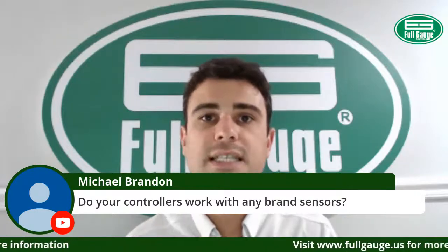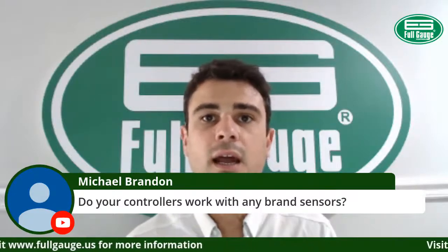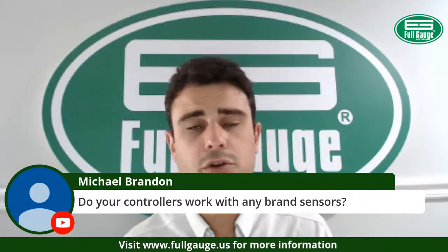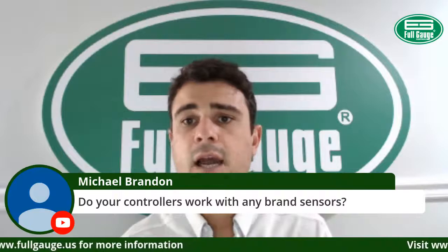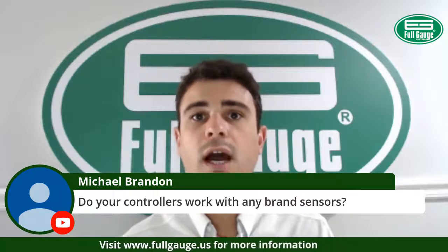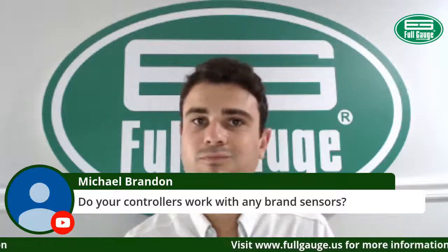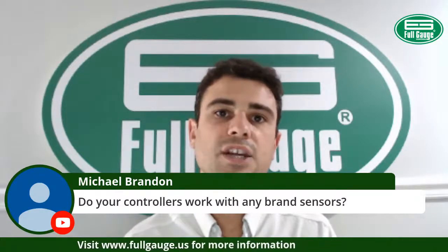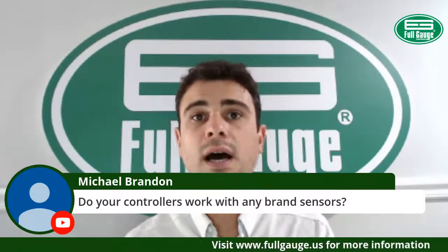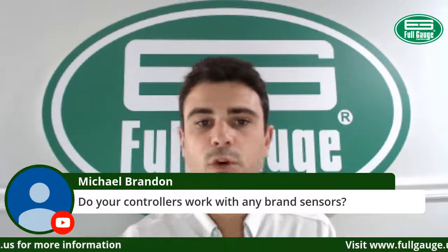If you don't want to rerun the sensor on the equipment, you can just cut the tip out, wire our Full Gauge sensor tip back in, and you're going to be using our sensor in that case. But anyway, if you do connect a different sensor manufacturer to our controller, it will work. However, you might have some temperature difference in the range. So the recommendation in that case is to make use of the offset function to calibrate that deviation which might be created by changing the sensor.